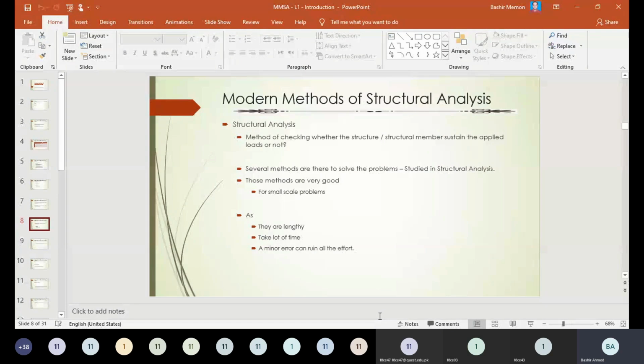And the tensile stresses, which are basically supposed to be carried by the steel, will not be carried by the steel, but concrete will be forced to carry those tensile stresses. On the other hand, we all know that concrete is very weak in tension. It cannot carry the tensile stresses, and as a result, cracks start developing in the zone of steel and concrete.